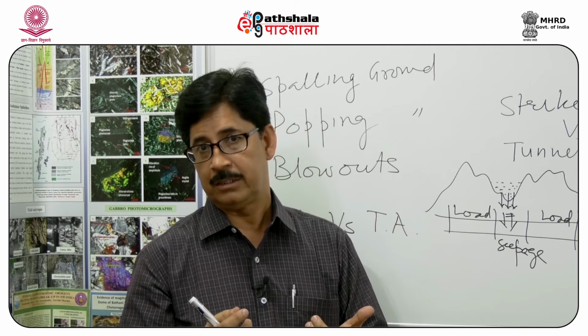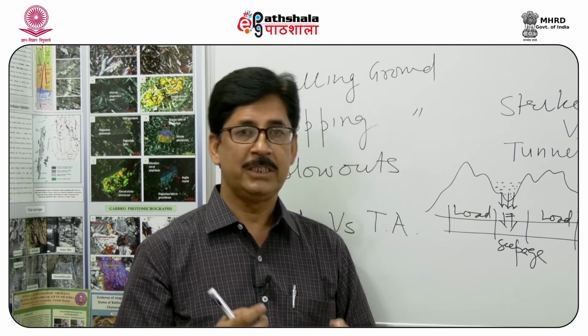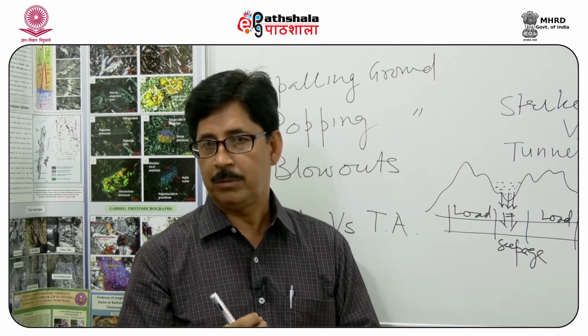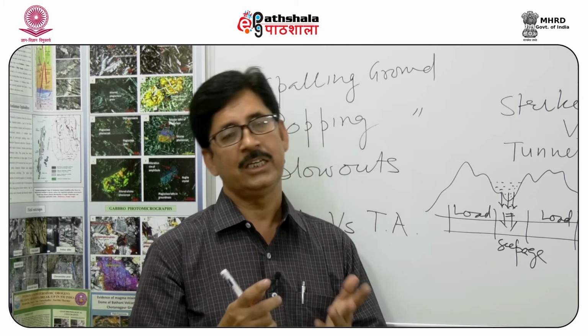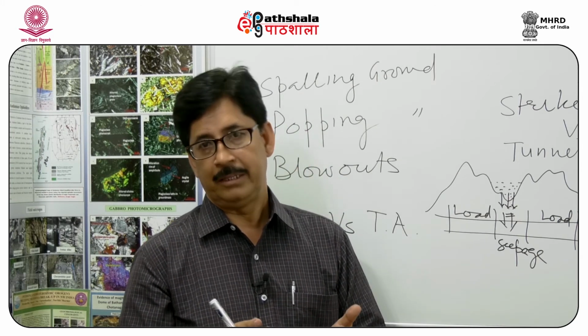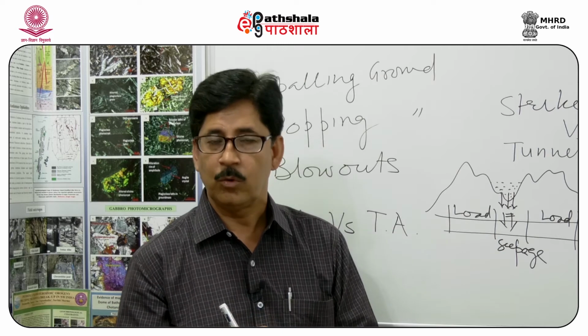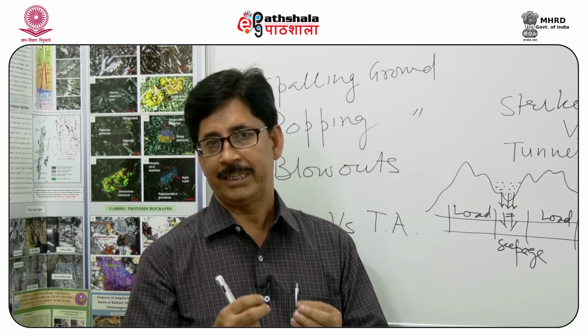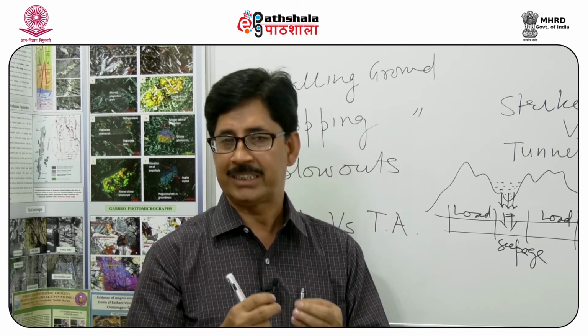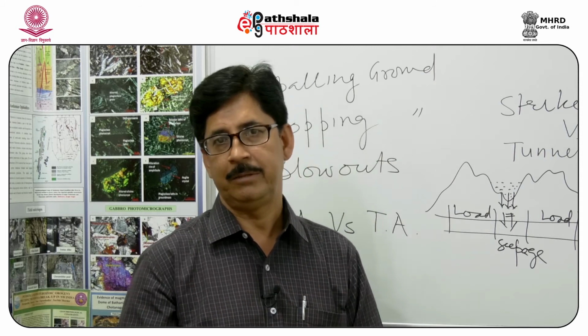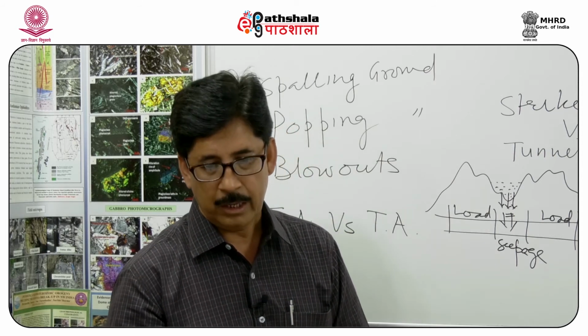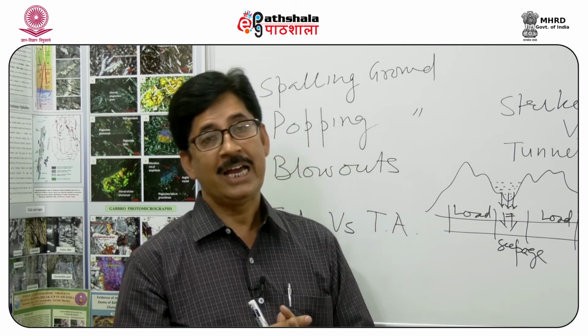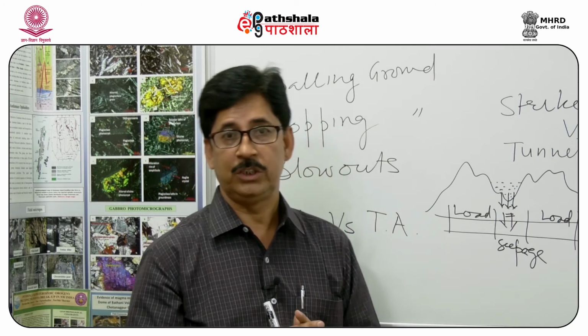Shear zones are very common. The presence of a shear zone will always be a problem because the rocks will be much weaker along them. They may also have a lot of groundwater. So we have to check them, we have to seal them, we have to excavate them, and we have to backfill with concrete. The most important structure which we have, that is the joints, which are ubiquitous.